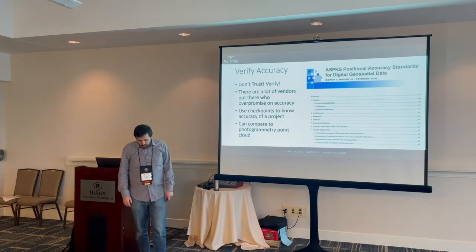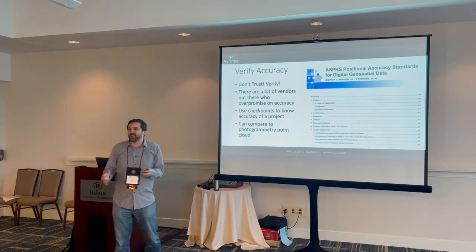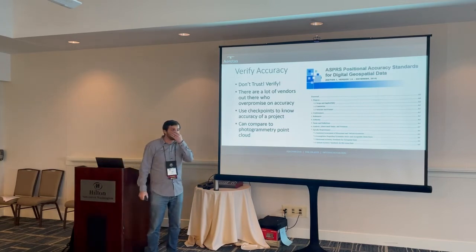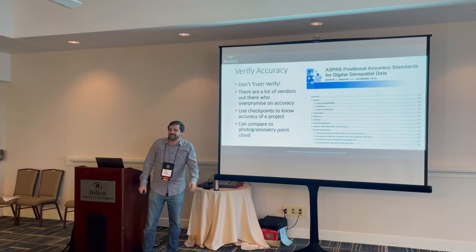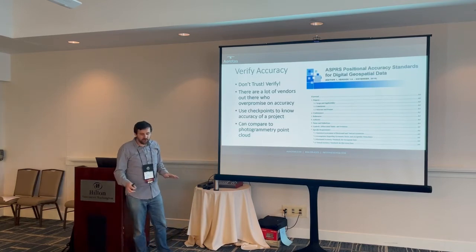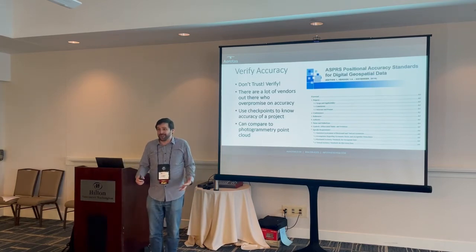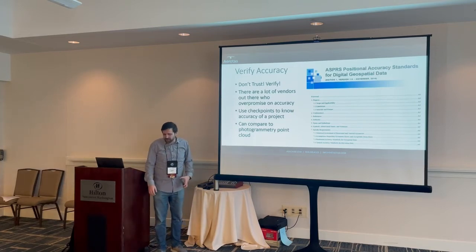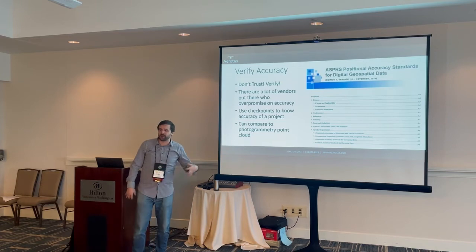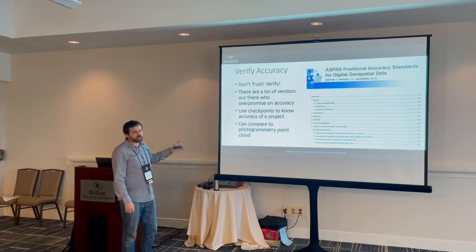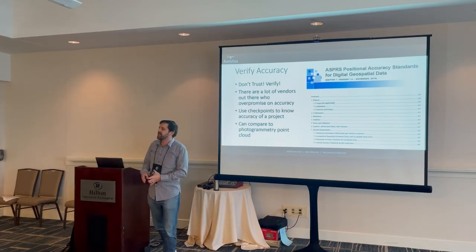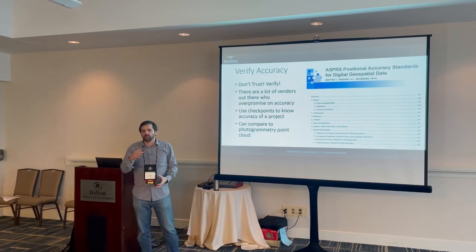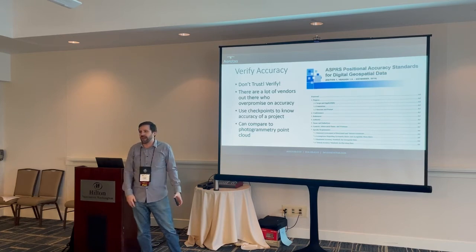Yep. Moving on from that, though, a lot of this is all about accuracy, right? One of the important things when we're talking about accuracy and even about these tests is always make sure you verify it. We're very good at processing all this stuff. I like to think I know a good chunk about actually processing LiDAR and photogrammetry data, but ultimately I always say, don't trust me. Trust the data, verify the data yourself. With all of these different systems and all of the different analyses that you could perform on it, what really matters at the end of the day is what's your final accuracy.